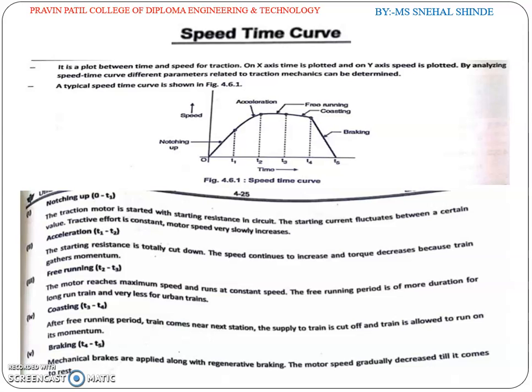This is because of reasons like the speed torque characteristics of the motor. As N increases, torque decreases. As N increases, train resistance increases very much.